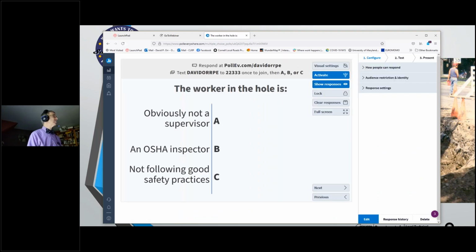And while that answer comes in, I'm going to reply here to your Q&A that you guys put in. Somebody put a note in here. Don't you consider seals and rejuvenators as part of construction? Joint seams should be sealed immediately. Rejuvenators have a limited window. Yes. Yes, any kind of rejuvenators or even emulsions need to be part of the overall construction process as well as the preservation process later on.